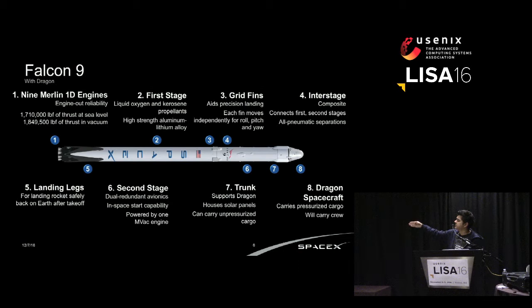And then there's a dome at the top that is the oxygen tank, what we call the ox dome. Then you've got this interstage where you've got the grid fins sticking out. And then the nozzle of the second stage is nestled down in the interstage. And then the second stage begins. In this photo, we've got Dragon on top of the second stage, and the second stage is made up, again, of a fuel and oxidizer tank and 1 main engine.